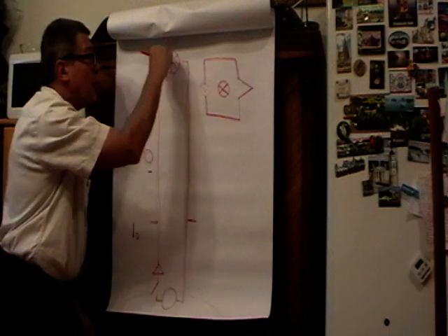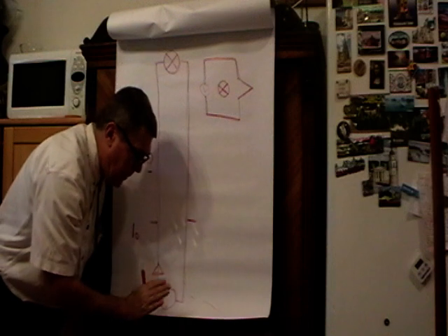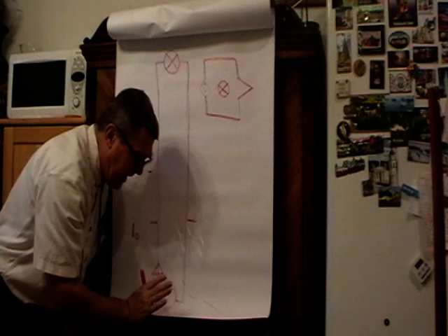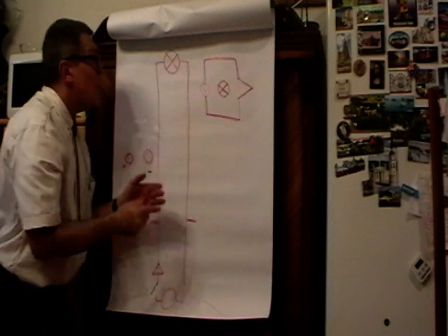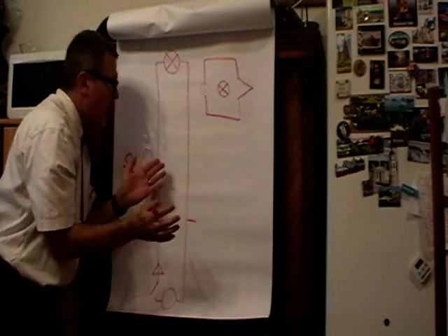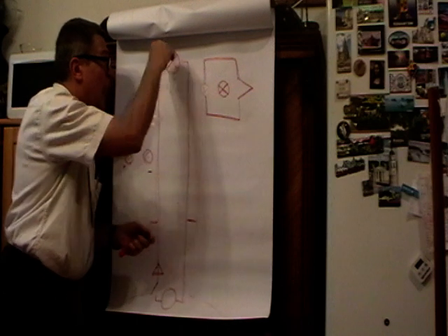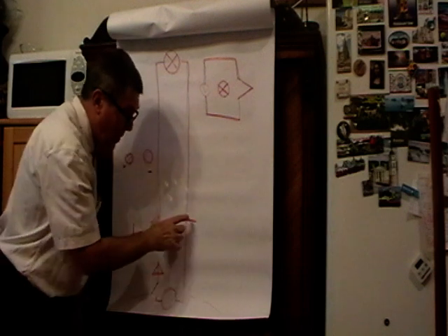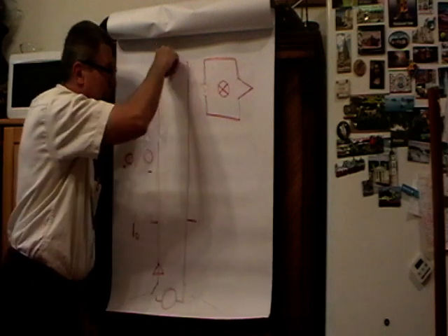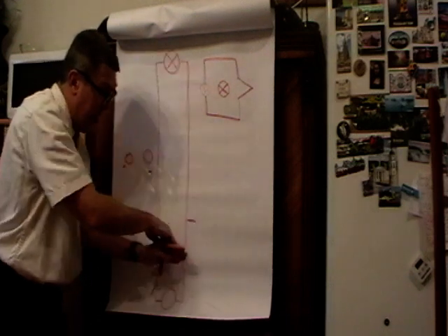So after this reflected wave gets to the source, he would have the first rough idea about the load at the end of the line. And talking in waves of current and voltage, we would have now another wave which has an opposite voltage, so that it cancels the voltage over the line as it passes back.